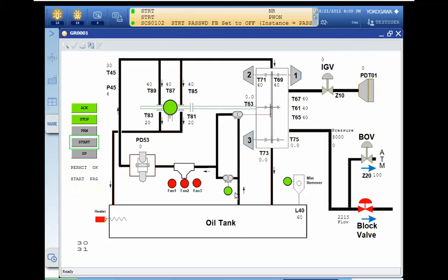There's some option to turn on the auxiliary oil pump again based on this pressure. If this pressure is dropping to some level, we can turn this oil pump on in order to compensate the oil pressure. So the set point for pressure is 8K, 8 bar.